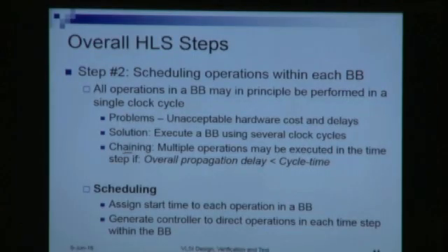Okay. So what is scheduling as such? The scheduling problem is to assign a start time to each operation in the basic block and generate the controller to direct operations in each time step within the basic block. So what are we doing? We are assigning a time step to each operation in the basic block.